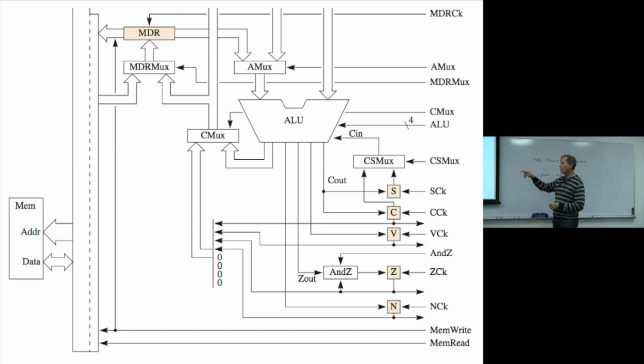And furthermore, the C out of the ALU, where does that go? It goes to the shadow and the carry. It taps off there. Right. Here, we can do a close-up of that. Notice that the C out here goes to both the shadow and the carry. So which one is it going to get clocked into?